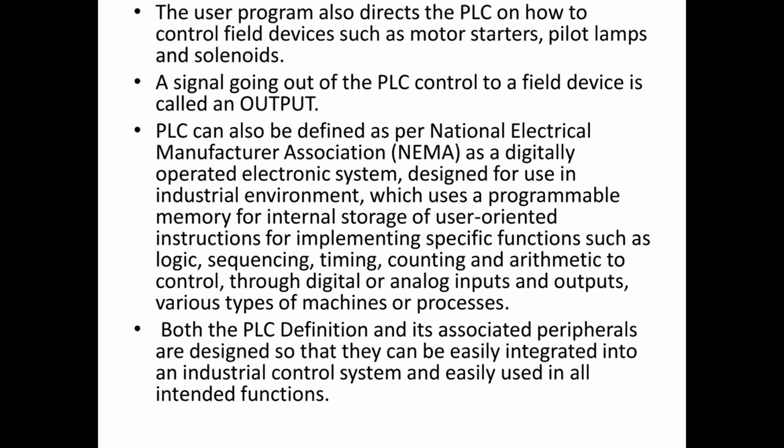It uses a programmable memory for internal storage of user-oriented instructions for implementing specific functions such as logic, sequencing, timing, counting, and arithmetic, to control through digital or analog inputs and outputs various types of machines or processes. Both the PLC and its associated peripherals are designed so that they can be easily integrated into an industrial control system and easily used in their intended functions.